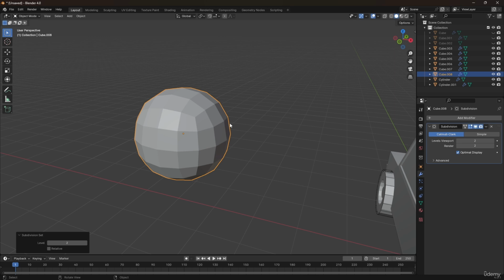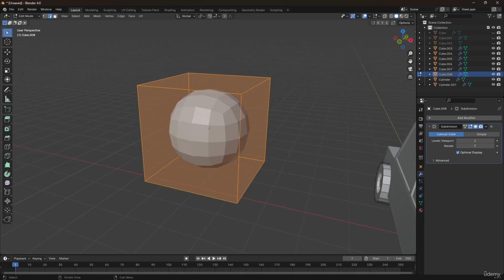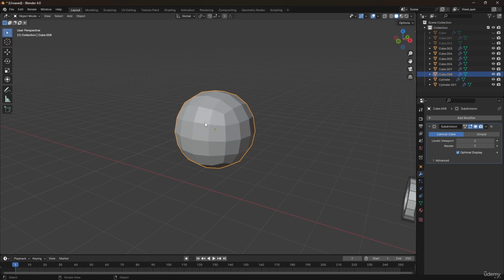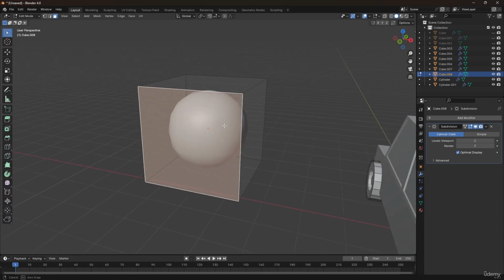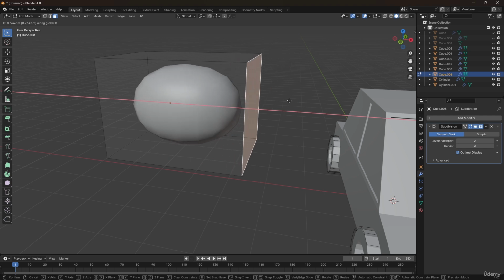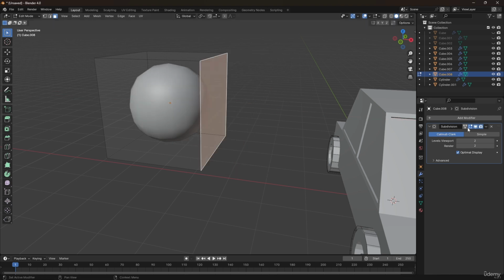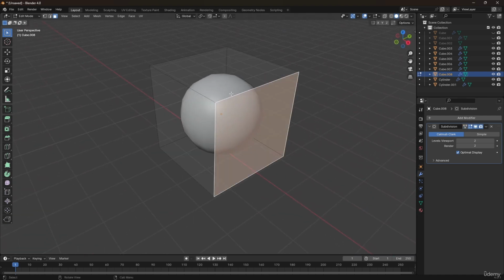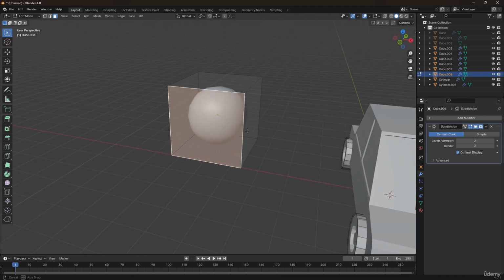And the reason why we use this is that if I go into edit mode, you can see even though this object is very round and smooth, let's right click and shade it smooth in object mode. So editing this would be much easier. I can just select one face and move it around. But when we apply this modifier, let's click on this icon, and you can see this would be the final geometry of this object. So the reason we use this often is that if you have a very organic object, you can still work on a very small number of vertices.